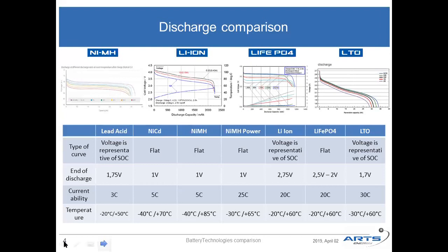According to the end of discharge, voltage is not the same according to the different technologies, but it is also in relation with the voltage of charge. So you can see that there are different values. What is important to keep in mind is that according to power, lithium ion delivers a higher power compared to the other technologies, with the exception of the nickel metal hydride power, a technology which is designed and dedicated to power applications.